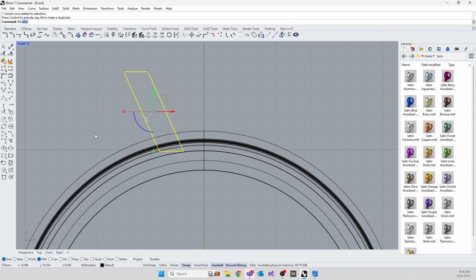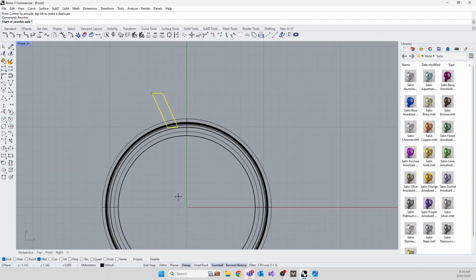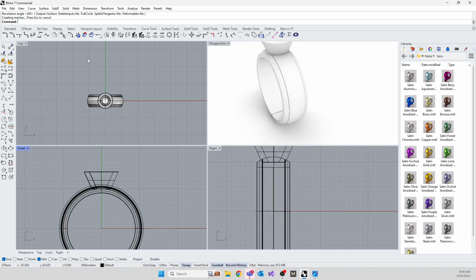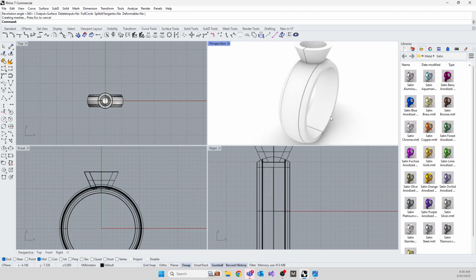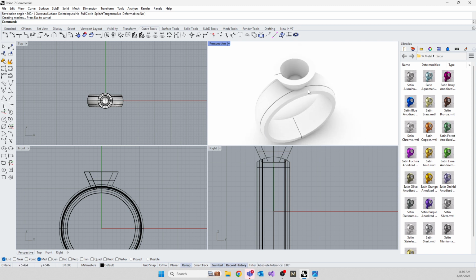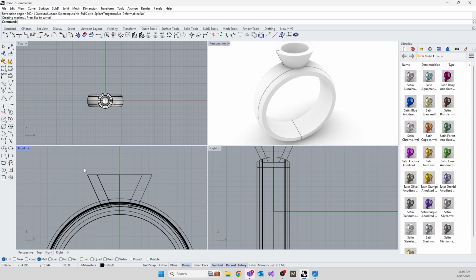And I'm going to run the revolve command. This time, this is my central axis from 0 directly upwards, like that. And I want to go all the way around. And I just made a setting for the ring. Try to do that with sweep. It would take forever and the geometry would be really messy. So revolve can do anything, plus also, next lesson we'll get into history. The quick short version of history is, because this was drawn with history, you can do this and you see the setting